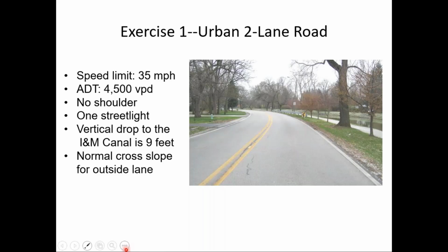And I can tell you what they actually did here. They did extend the guardrail around the whole length of the curve. They did install a curve warning sign with an advisory speed because there was none. Behind the guardrail, they installed chevrons, as someone mentioned, for the full length of the curve rather than just one.